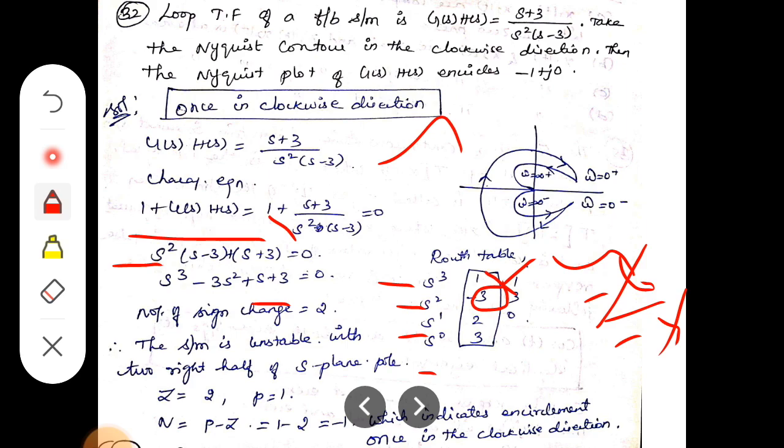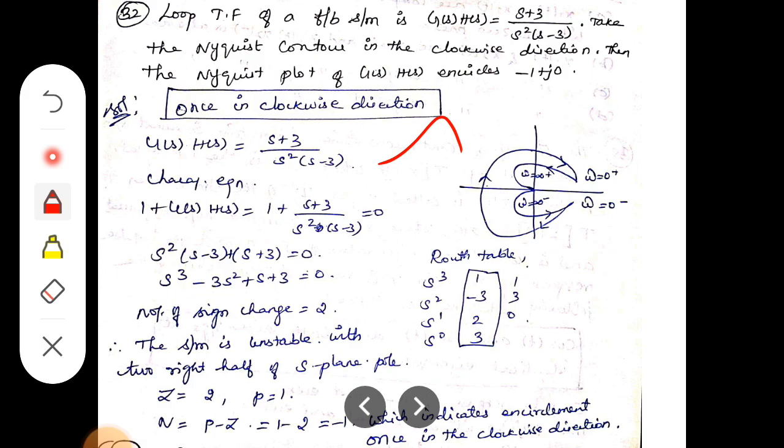Similarly we calculate this one. So from this equation, we clearly know the function of Routh's criterion. It shows that once a sign change occurs, the system is said to be an unstable system, so the poles lie on the right half of the S plane.